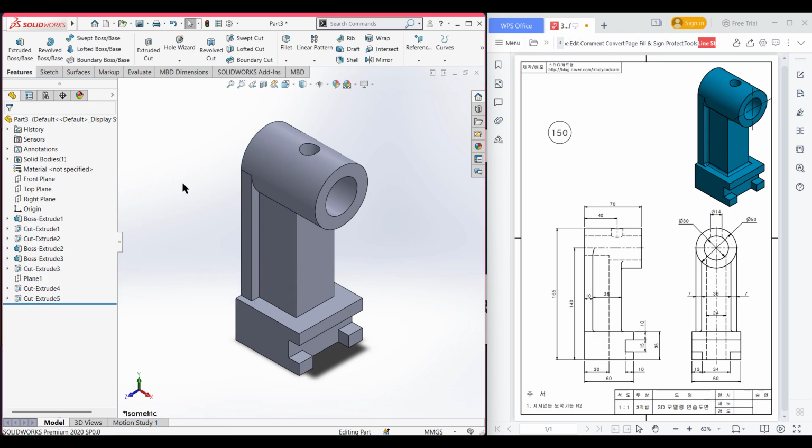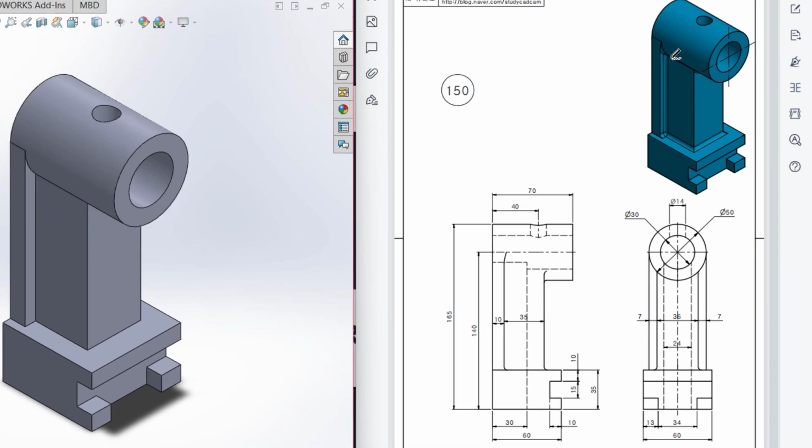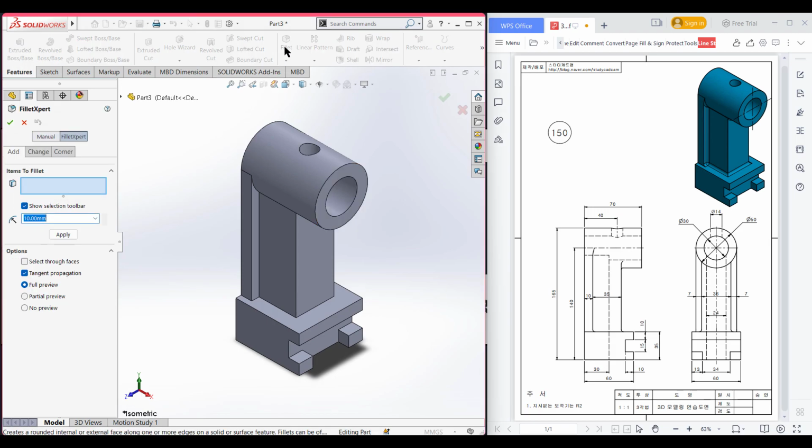So we have done our shape, but it's time for the filleting. So if we see in the main sketch here, we have some fillet here and here, okay, and here also. And in the drawing, the fillet is not given. So I am assuming as this length will be 7 units, so I'm assuming the half distance will be almost 3 unit. So I'm assuming the fillet is 3 unit, okay. So I'm selecting the fillet option, and from the fillet option, select the dimension to 3 unit. Now press enter. Now zoom in.